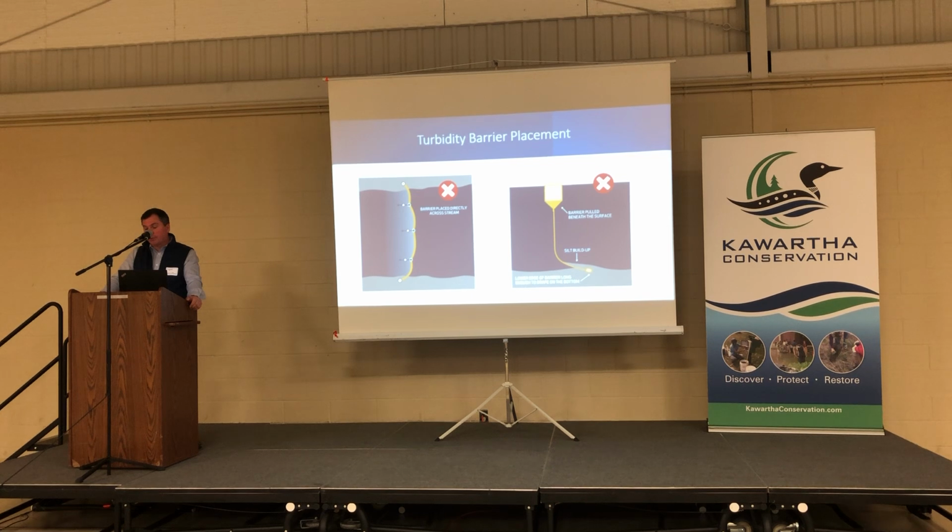And then just to repeat, settling the curtain directly on the bottom does leave a chance for siltation to take place, where the sediment is sitting directly on the curtain. And over time, if you get enough sediment, that will actually pull the float underneath the water.